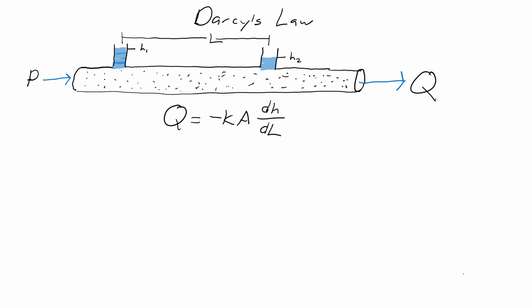So you'll construct a topographic profile first, which shows what the topography looks like. You should see areas where it goes up to mountain peaks and areas where it goes down to river bottoms. So there'll be some undulating topography. But what is different with a geologic cross-section is that beneath that topographic profile, you will show what the rock units are doing. And you're going to get that information from the geologic map.